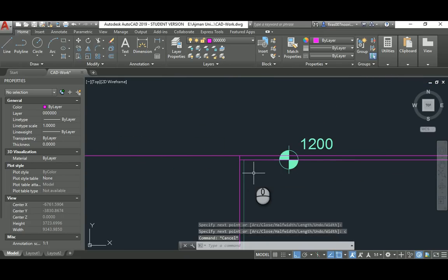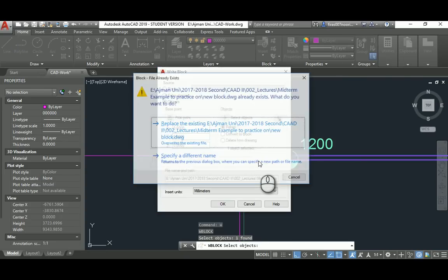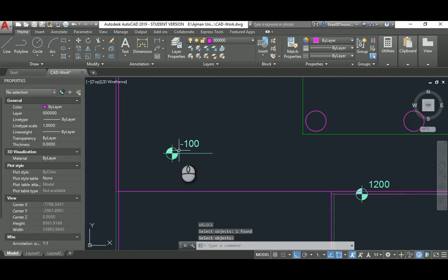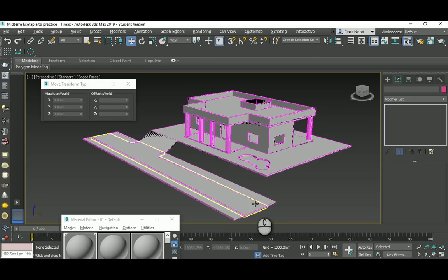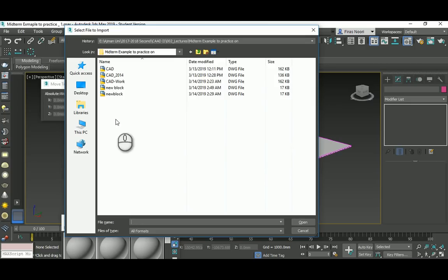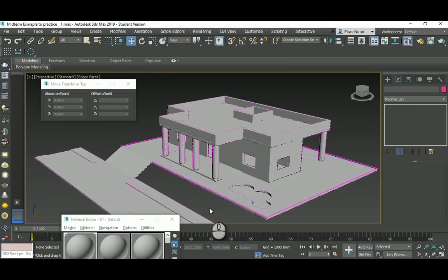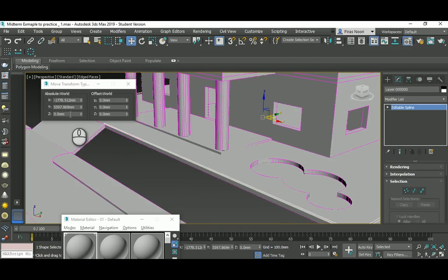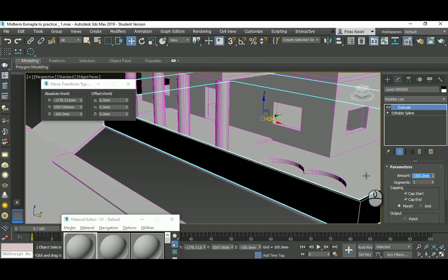Closing it, right block. Again, it's a fence, so it's an external wall. So you should see the lowest point, which is minus 100 to 1200. So you should place it at minus 100. Let's say, place it minus 100, and then add an extrusion of 1300, and then add that to it.